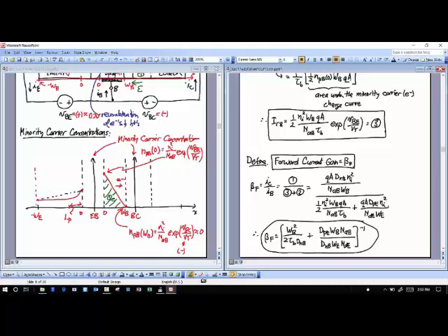Currents 3 and 2 are the recombination current, this current right here, which you can see is 3 plus 2, the injected charge, and then the diffusion current that occurs in the emitter from the base. Okay? If I put all these equations together, I can come up with an expression for this beta F, which you can see depends on these doping concentrations, NDE and NAB. This whole thing is to the -1, right?